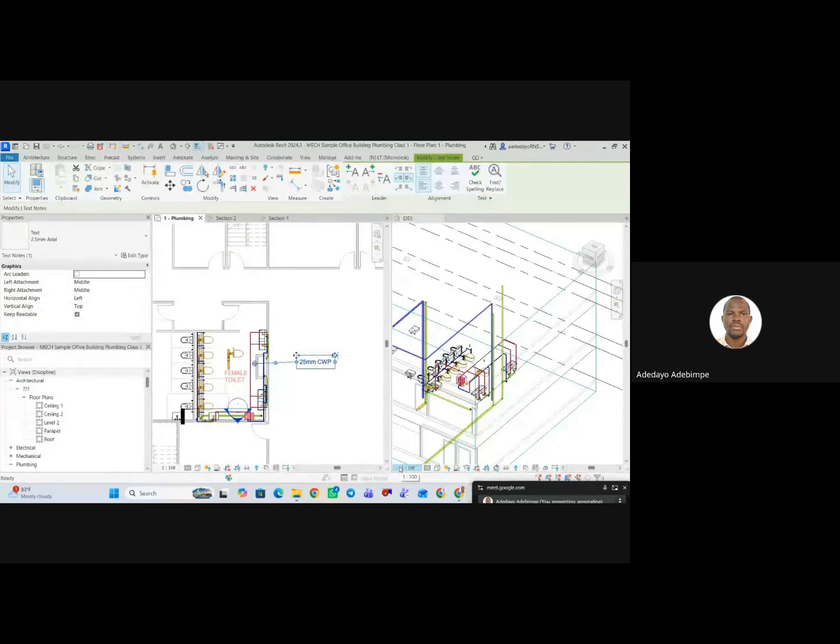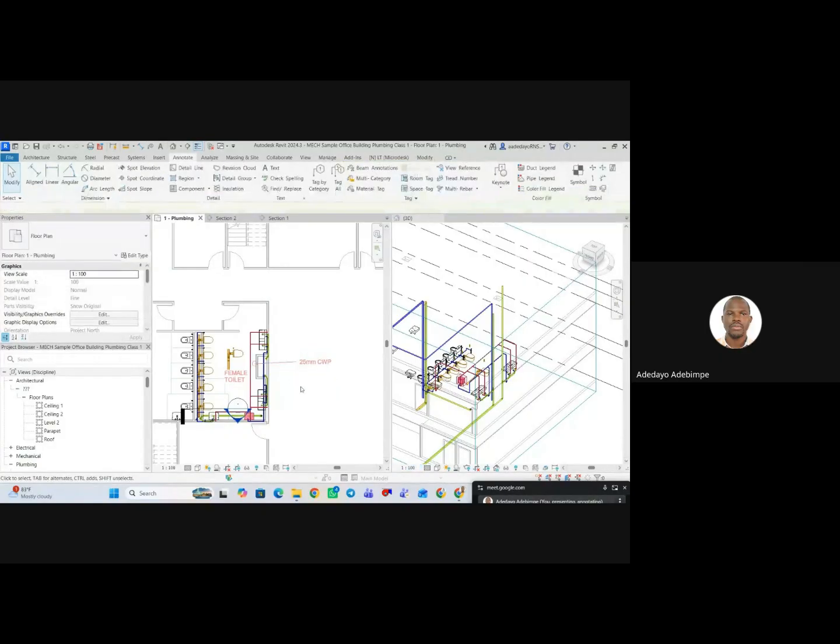I have two sheets, both of them A1. On one view I have 1:50, on another view I have 1:100. To ensure the text stays the same, on my 1:50 sheet I need my text to be 4 mm, and on my 1:100 sheet I need my text to be 2.5 to maintain consistency in text size.